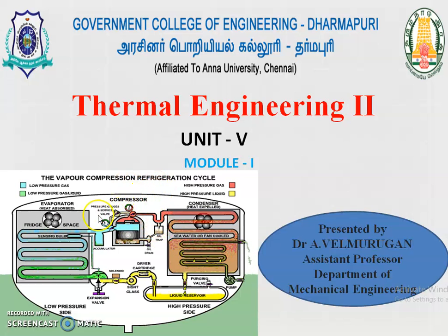The working principle of the vapor compression refrigeration system is this: low temperature and low pressure vapor from the evaporator enters the compressor. In the compressor, the vapor is compressed and delivered as high pressure and high temperature vapor, which goes to the condenser.